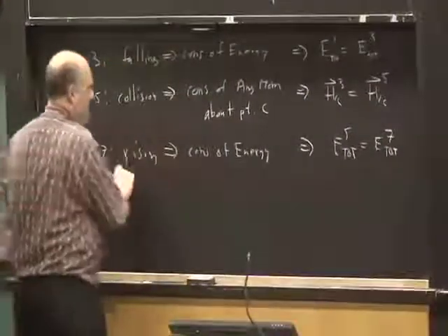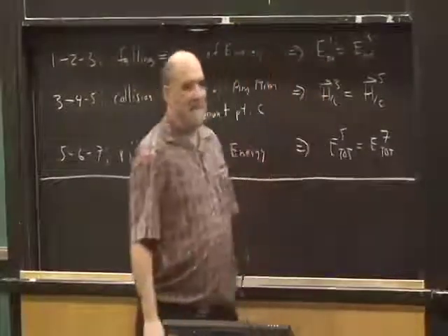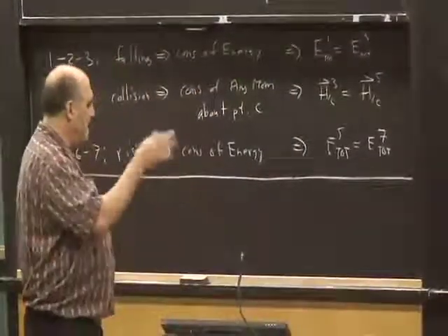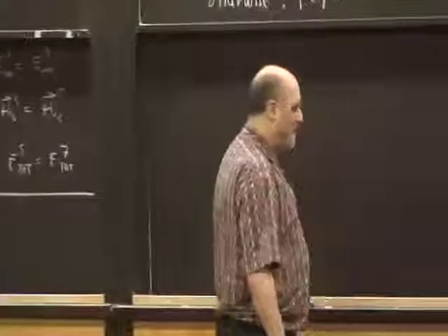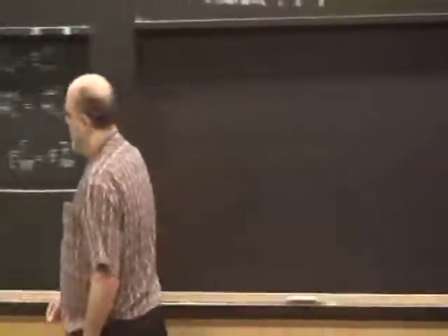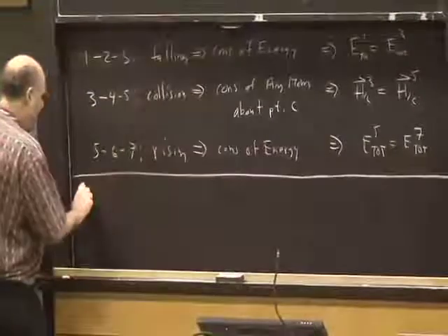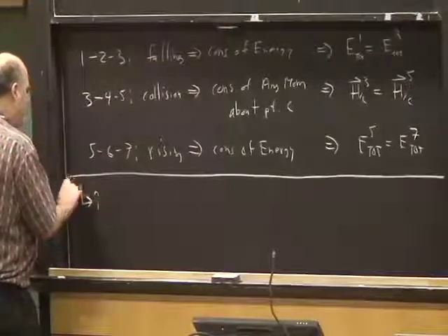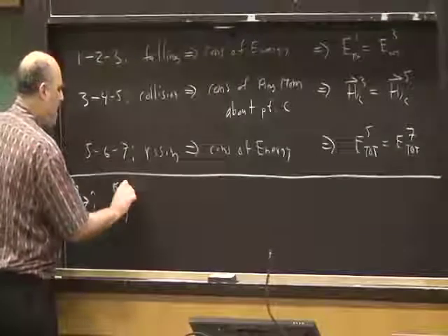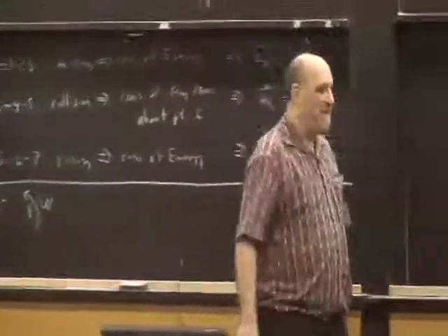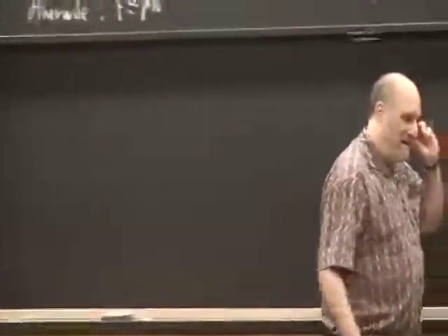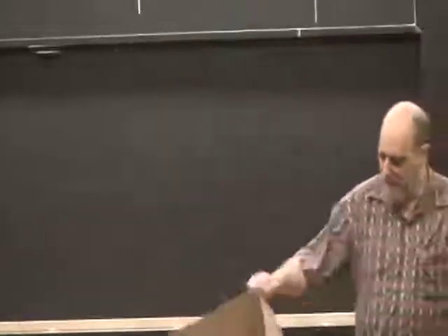Okay, so now let's flesh this out in terms of the variables. This system has 1 degree of freedom, so we can keep track of it with some angle and some angular rate. Let's pick a coordinate system, say, like this, with I and J. Implicit with that coordinate system, if we want things to work out with cross products and so on, is that angular velocity is going to be positive in the counterclockwise direction. Unfortunately, the way I set up this demo, I have it moving in the clockwise direction, so all of our angular velocities are going to be negative. And so, sorry about that.